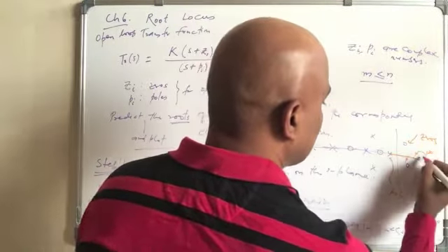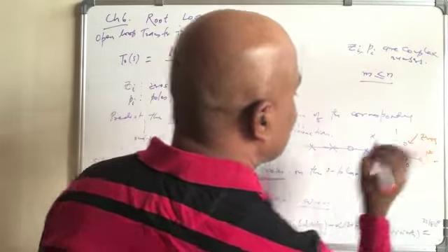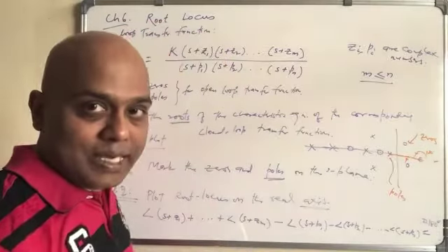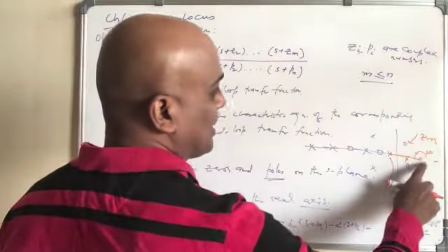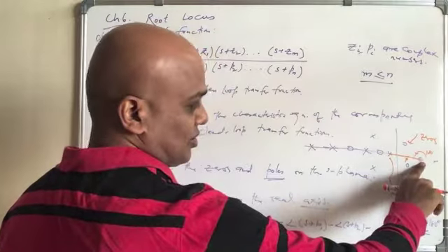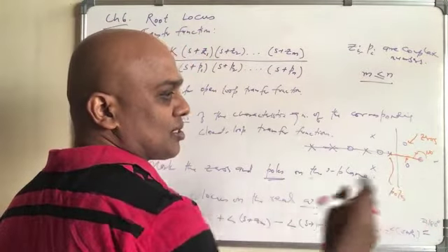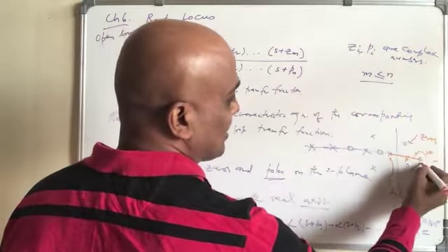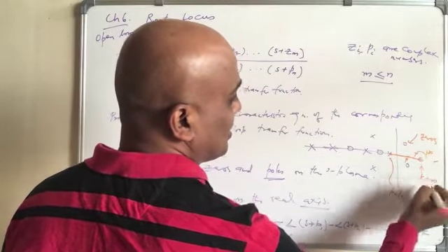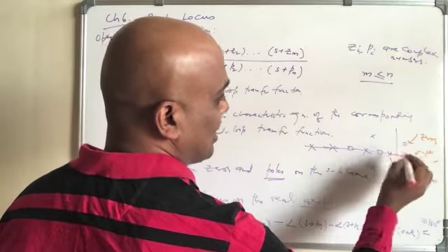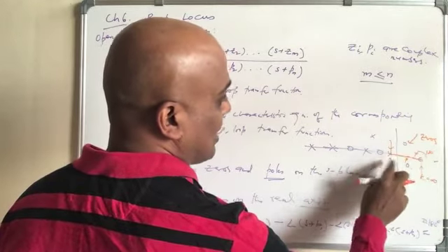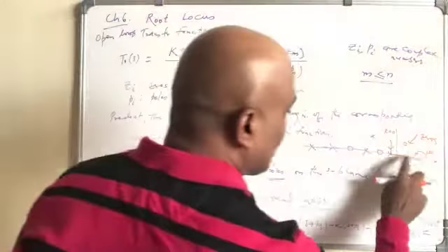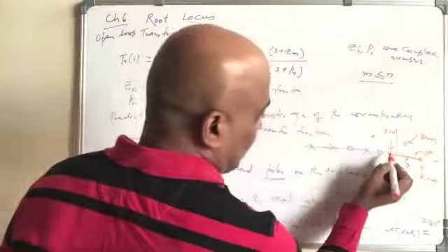Yeah. So here to here is the root locus, and you know that at the cross it is k equal to 0, and at the zeros, k equal to infinity, right? So that we know there's k equal to infinity where the zeros are, and when there's a cross, there k equal to 0. That we have studied already. So like this. Now look at this one.